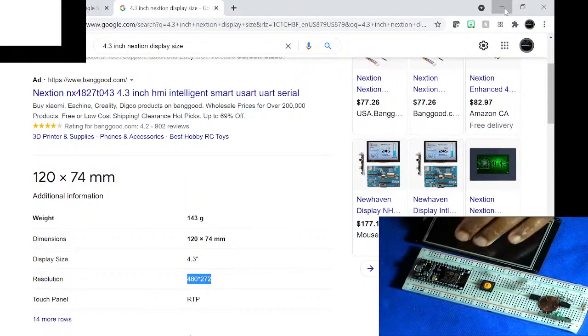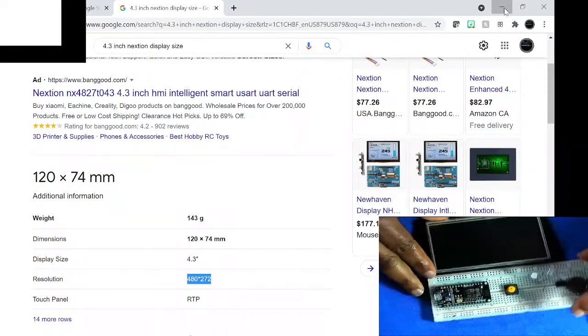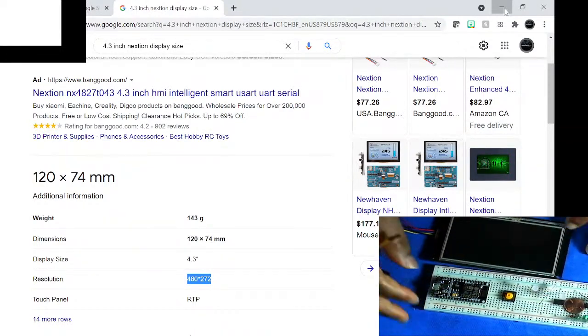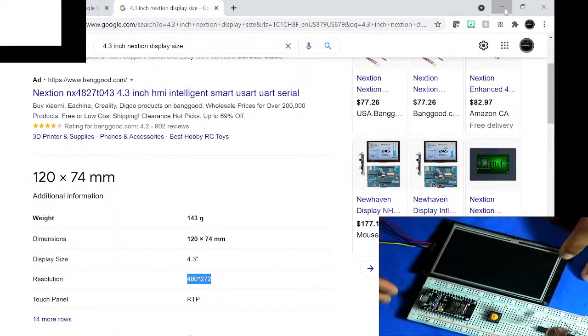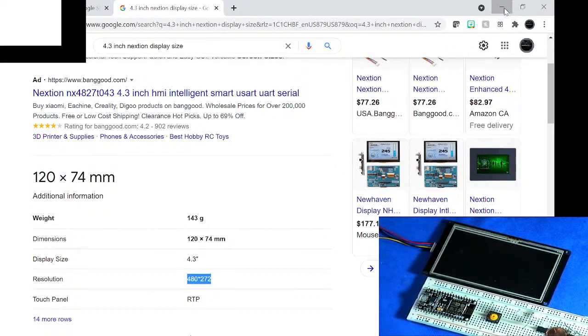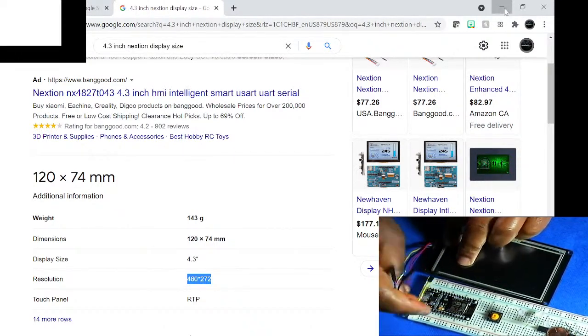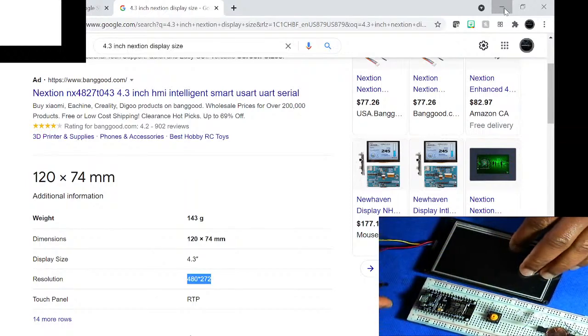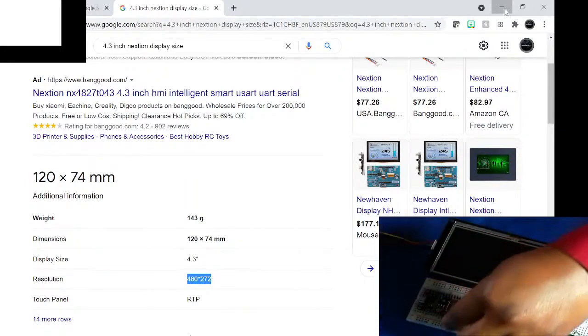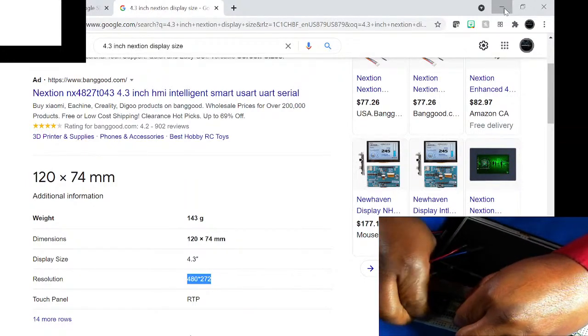You have a transmit, you have a receive in both of them. So one transmit, one receive, and we're gonna connect them together. So the power this time around is going to come through the USB, so we don't really need to have an external USB plug. So everything is going to come from the Arduino right here. So I don't have to have it here on the board.